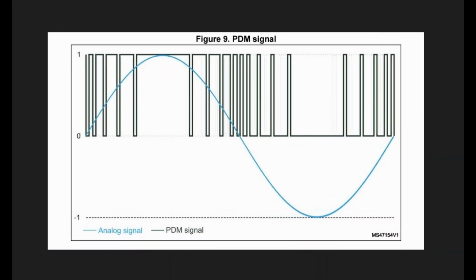So let's talk a little bit about the TL494 and Pulse Duration Modulation. Now, as you know, you can certainly represent a sine wave very effectively using PDM. And we can see in this diagram that we can go positive and we can go negative. That's going to be very important when we're doing AM modulation. We need to have upward and downward swing. And we're going to have to handle negative peaks as we get closer to the modulator section. You'll see how we handle that.